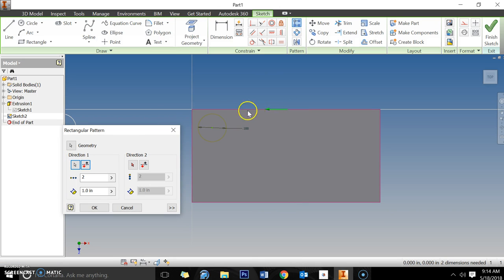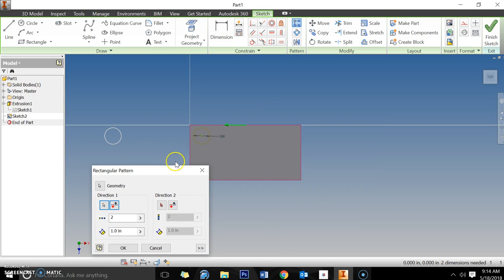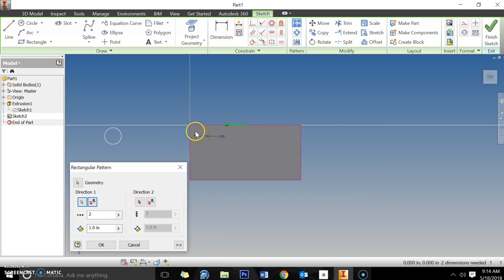Good. So you know it's selected when you get this green arrow. As of now, I'm just going to show you the arrow is pointing in the wrong direction. I'm going to get multiple circles here off of my drawing, so I'm going to flip-flop that. That's the next one, next to the cursor, it's the flip direction. So now you can see, okay, it's in the right direction.